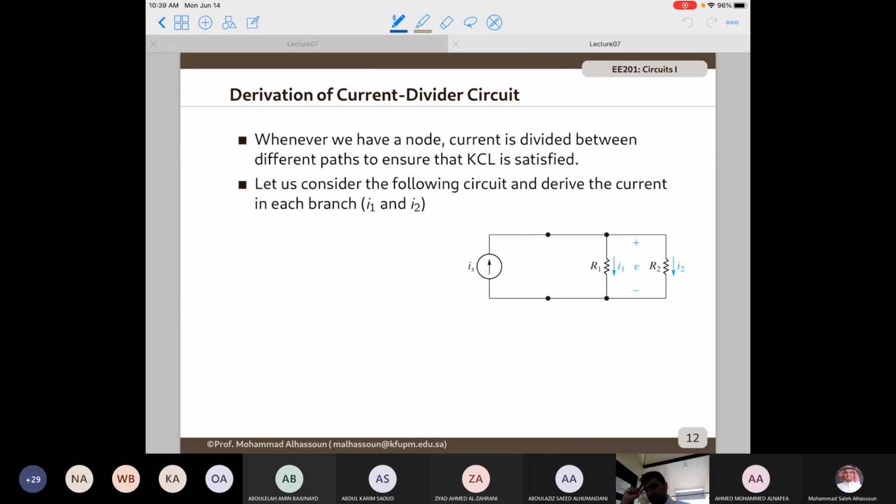So we had a situation, or if you remember, we talked about a circuit that divides the voltage, which requires having resistors in series. Now let's talk about a circuit that divides current, which again requires, we cannot use a series combination, because remember that if you have two resistors connected in series, they must share the same current. This is a simple result of Kirchhoff's current law.